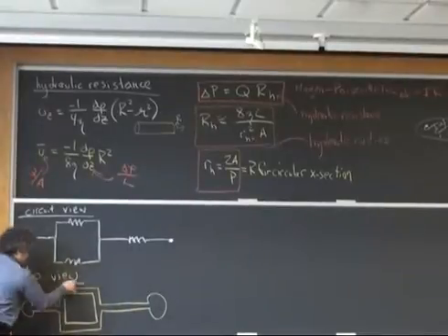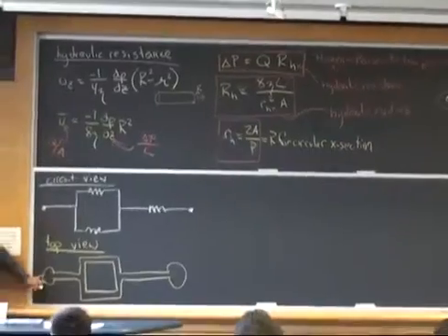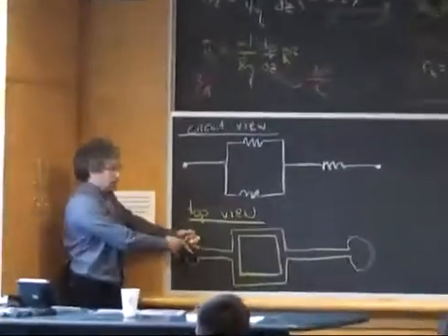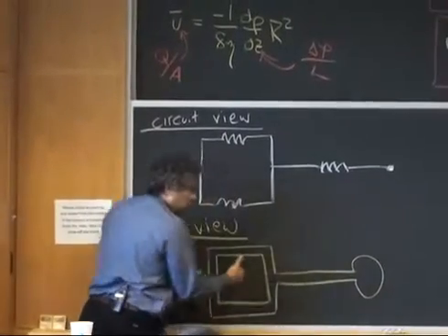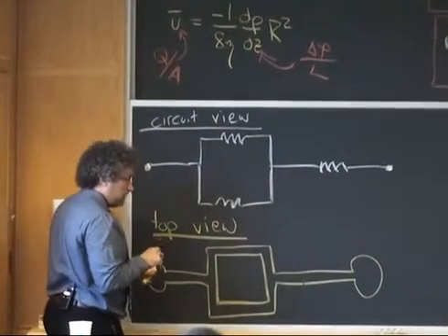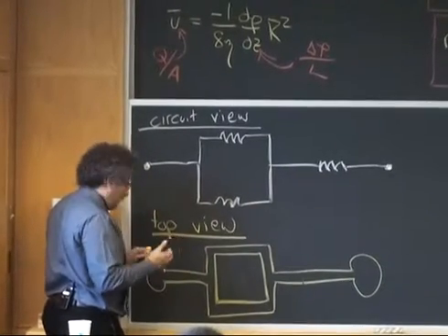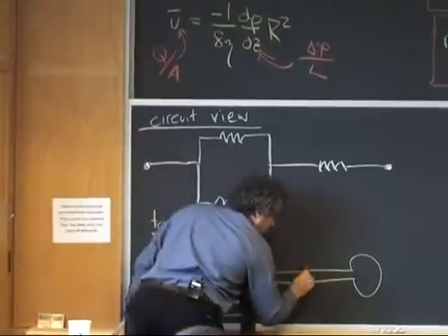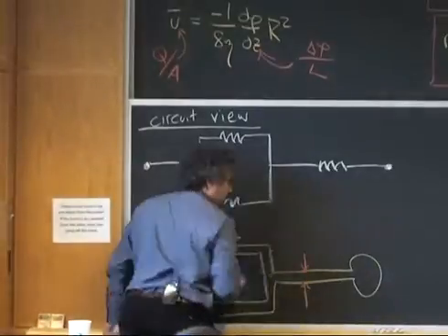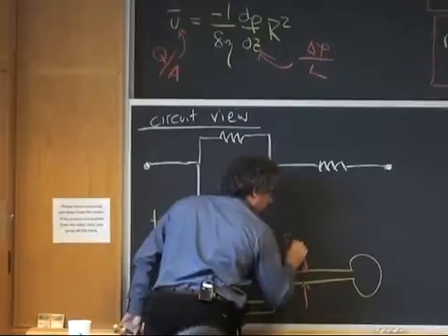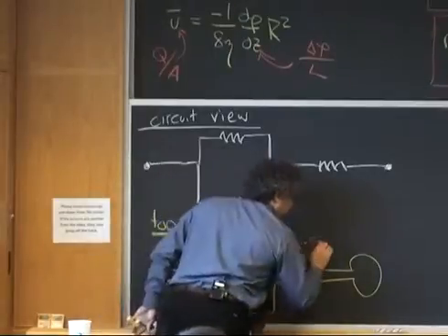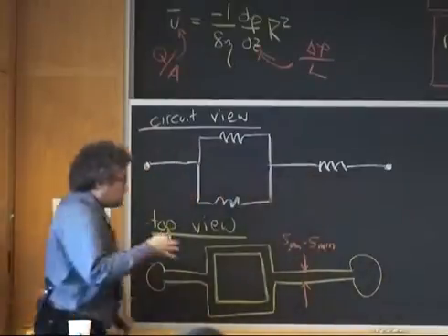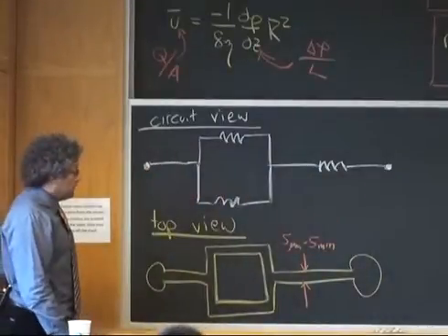So if I go and make a microfluidic device, and I look at it from the top, I may have a shape that looks a little bit like this. These channels will have some characteristic width. If you do routine photolithographic fabrication, the characteristic size of these channels might range from about 5 microns all the way up to, I guess you could do maybe 5 millimeters. That varies a little bit based on the material that you're using.